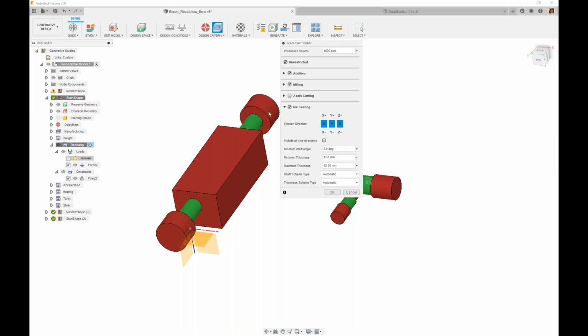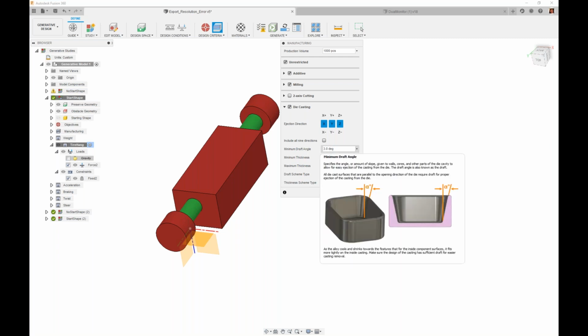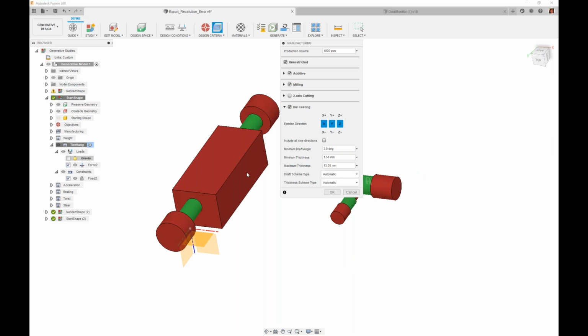For a die cast model, when we look along a given axis, we take into account the draft angle. Perhaps, for an extrusion part, that draft angle would be 0 because it's a continual feed of material. So you might be able to leverage the die casting results as a method of getting an extrudable part.